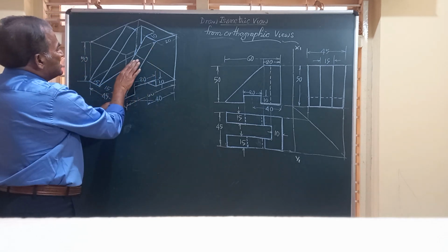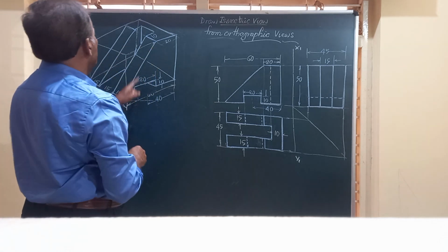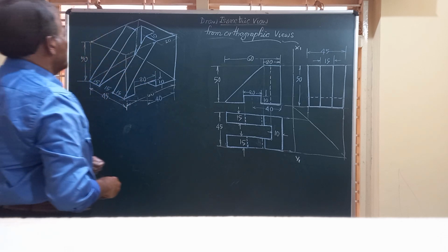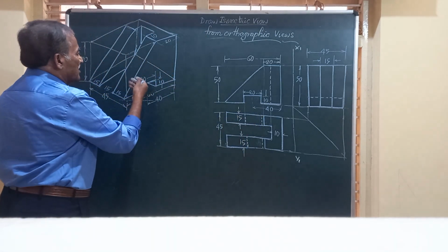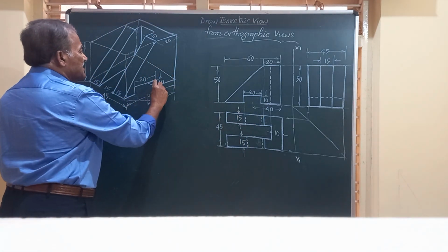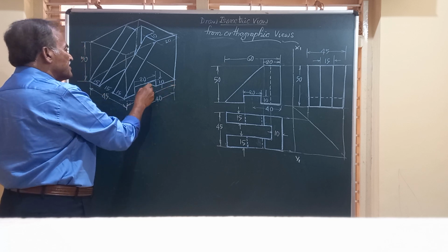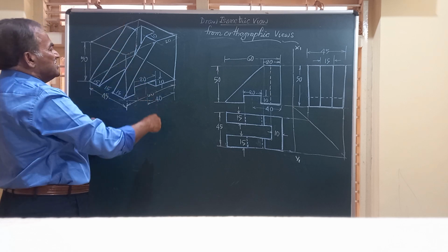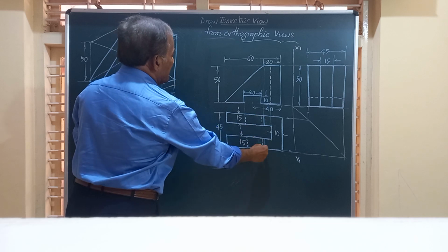This line indicates surface 1, surface 2, and this surface also. It is showing all these, friends. And then after that, you have got a slot here. The slot has a width of 20, thickness 10, cut at a distance of 40 millimeter from the extreme end, that I have shown in the slot, and that is seen as two dotted lines. This I have already explained.